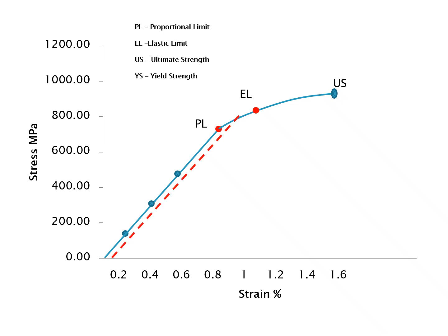In some cases, we will not be able to differentiate the straight or the curved portion of the graph clearly. So in these cases, to clearly differentiate the point of elastic limit, another measure called yield strength is used. This is usually drawn as a line which is parallel to the straight portion of the curve, and the point where this line meets the curve is called the yield strength. So it is used sometimes as a replacement or an alternative to the point of elastic limit.